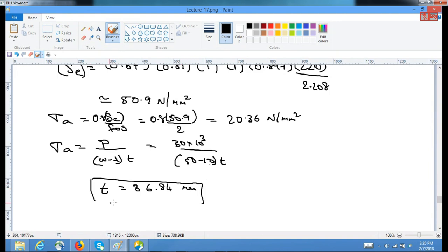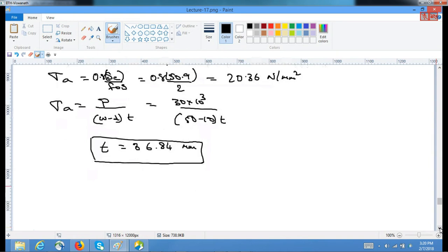Make sure we obtain the thickness such that it can take a complete reversal of load from 30 kilonewtons to minus 30 kilonewtons under the fluctuating load. So this is the case for the infinite life. Now the second example we'll deal with today is a finite life problem.